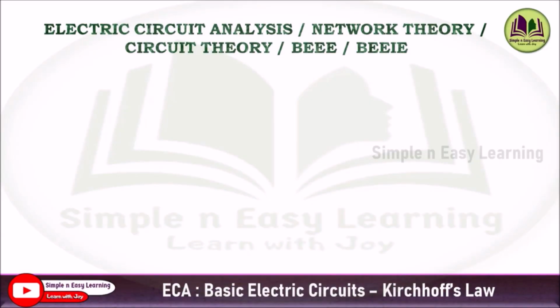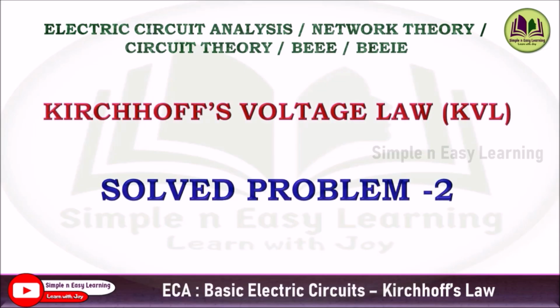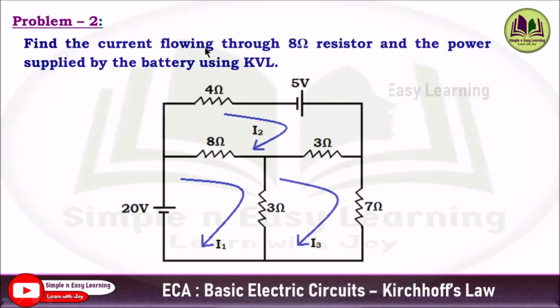In electric circuit analysis, or network theory, or circuit theory, the basic electrical engineering, Kirchhoff's voltage law solved problem 2. Find the current flowing through the 8 ohm resistor and the power supplied by the battery using KVL. So here there are 3 loops.